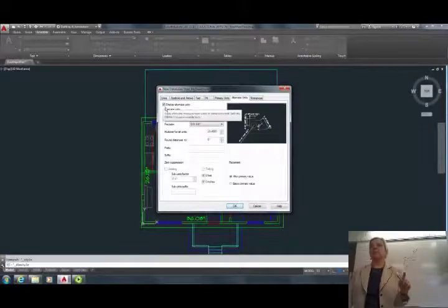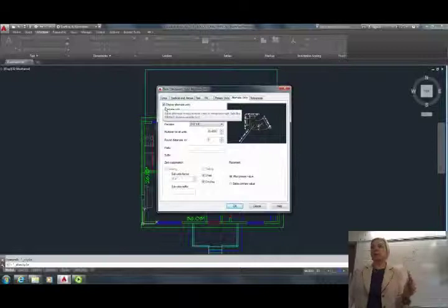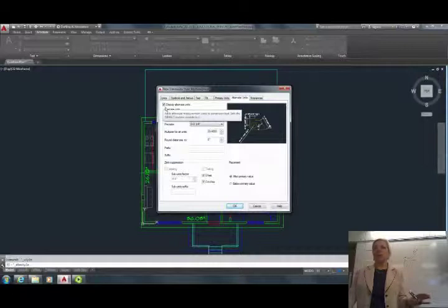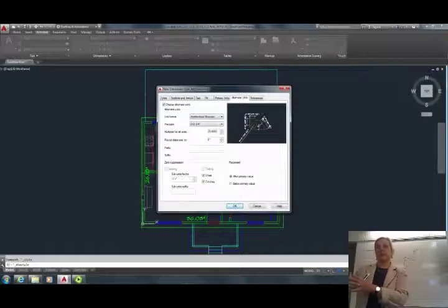function of AutoCAD for meetings with people who work in the other system. You could have a client that has been working only with metric. You're doing the imperial set, and they're saying, well, what is it in meters? And you don't know. If you go into a meeting with that person, if you put that radio button on, in brackets, you will get the alternate dimensions.